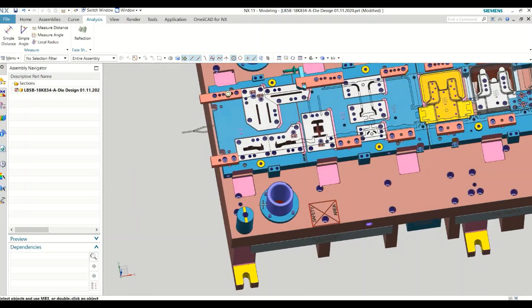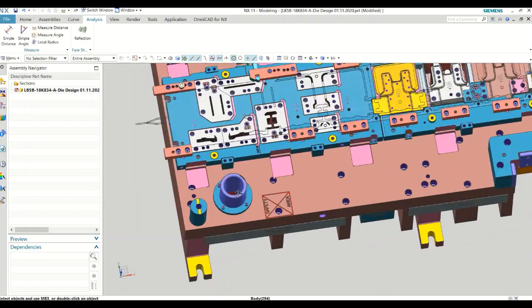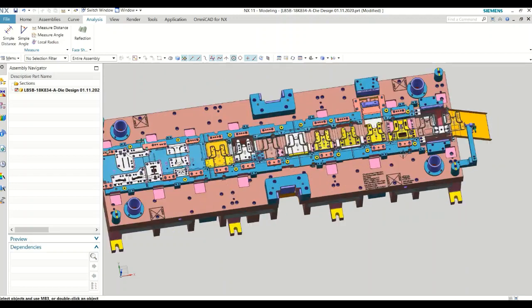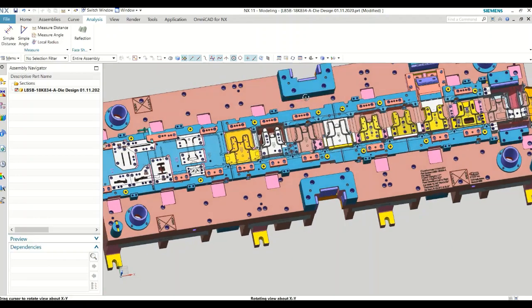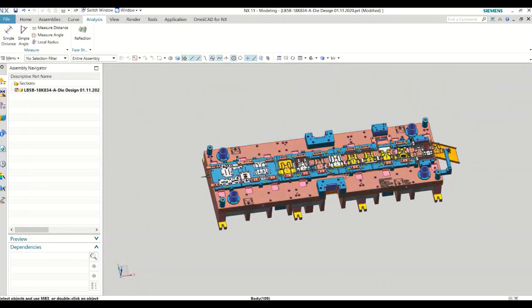Okay. And these four, it's easy for you to understand. These four are nothing but guide pins and guide bushes, guide bushes for the upper die. And it has multiple forms. To control the forces, we have these two lower guide blocks. We have a guide post in the upper die which comes in, and that is the way we try to balance out the thrusts because of the shape of the part.